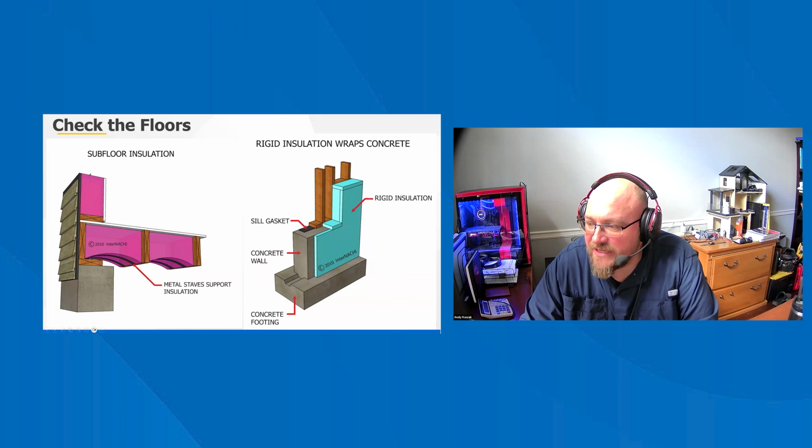Reflective systems are installed in a similar way to batt insulation. It is important to install reflective insulation properly for it to be effective. Sometimes reflective insulation will have flanges stapled to the framing members. This conductive material must not come into contact with any electrical current. You may find spray foam insulation at a floor system. The spray can do an excellent job of insulating and filling the spaces around electrical wires, pipes, and other obstructions.